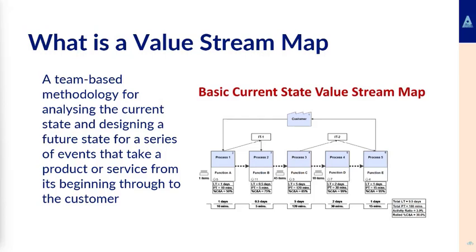If you have a repeatable part of the works on a project, it might be installing manholes, it might be concrete slabs or vertical reinforced concrete walls. Could be quite a lot of them. Could be piling foundations. You maybe have a number of them within your program. You could do a value stream map of what is the current state. How do we plan to do this? Or how have we just done it? And then say, well, is there an easier, faster way that we can do this? And can we reduce some of the processes or reduce the time in between each step?